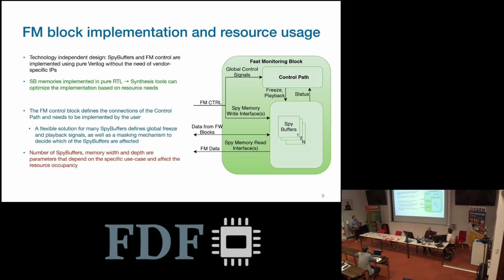It has been written in Verilog, and it doesn't need vendor-specific IP. And the synthesis tool, for instance for the Spybuffer memories, which are implemented in RTL, can just optimize the implementation based on what your FPGA has.